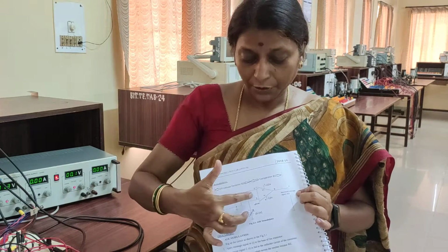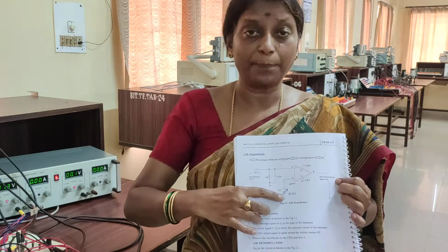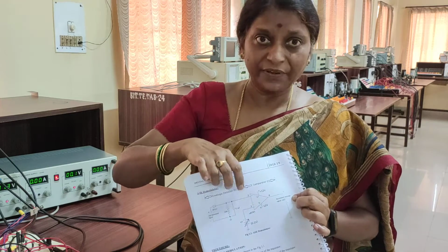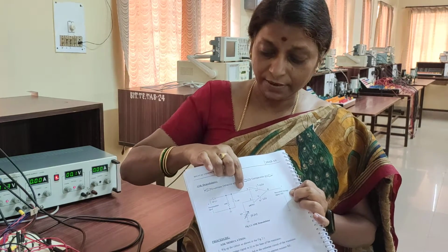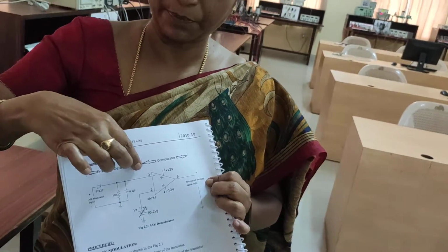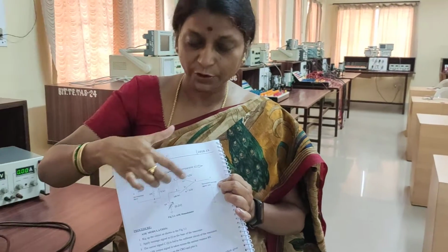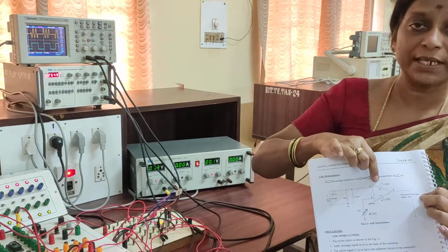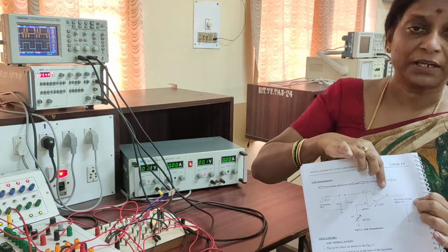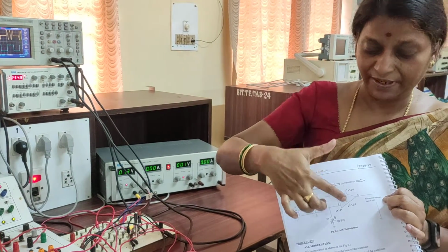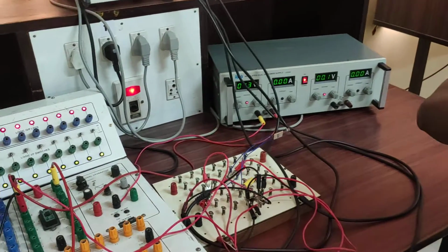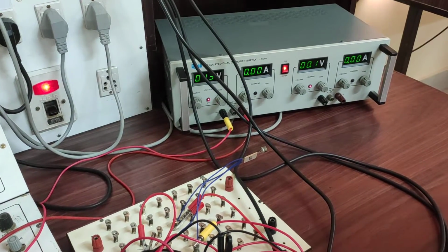So here to the pin number 2 or the inverting pin, we are applying a small bias here from the supply. So by controlling the bias signal, we can get the recovered message signal. So here when the envelope output is high, we can adjust the bias approximately half of the envelope what we are getting. So that will be comparing and you will get back your recovered signal. And since we are using a comparator, the amplitude which we will get at the output of the envelope detector and the comparator circuit will be high, since we are giving +12 and -12. So we get a saturation levels approximately 90% of the supply voltage. So frequency will remain the same as we have given 250 Hz.